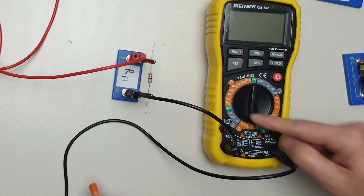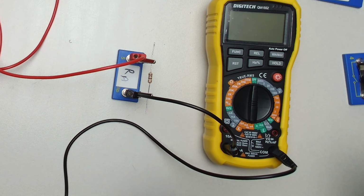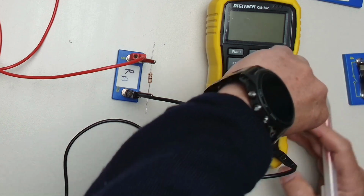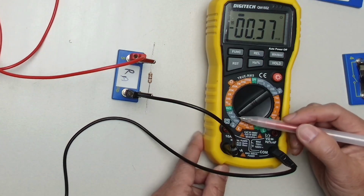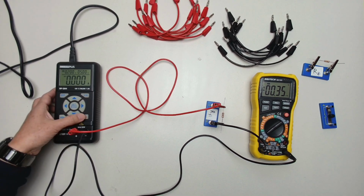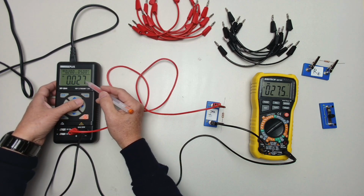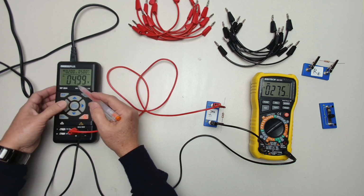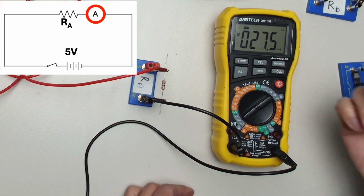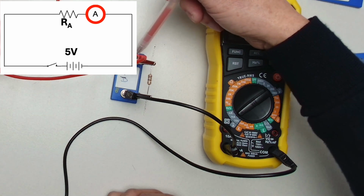Next, we want to know how we choose. Remember, this is the digital multimeter, multifunction. We have to turn this one into a current meter, which means it measures current. Turn this one here. The range we use is mA again. This is just the offset or stray. Now I turn this one on. And we can look at here, 27 milliamp, or we check here, 4.99 volt. And here, 27.5 milliamp, exactly the same number we measured before, when the current was passing through here.